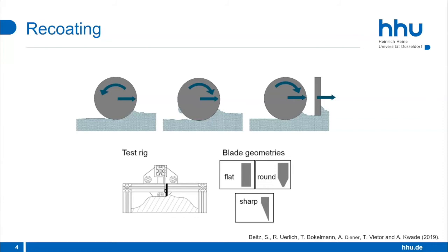It has been reported that a co-rotating roller, so this one in the middle, can lead to higher densities of the powder bed because you have a higher compression during the ongoing process, whereas you have a lower compression with this counter-rotating roller where the material is drawn upwards. There are some hybrid mechanisms that are possible that are able to create an even smoother surface, which is something that you're looking for. And if you don't have a roll available, so especially the cheaper benchtop machines for SLS